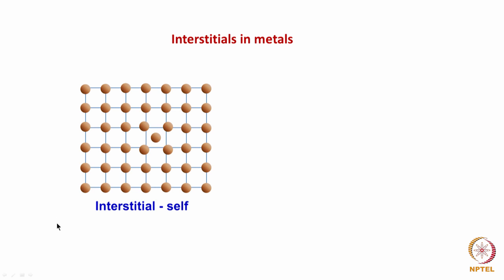Not only the strain, we are bringing atoms which are at equilibrium distance and putting another atom close by. So the repulsive forces between the atoms also will increase, and that will also be responsible for movement of atoms away from each other. That is how the distortion or the strain is generated around the defect position, locally.